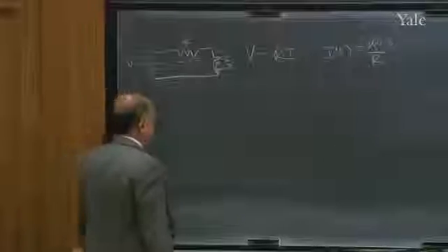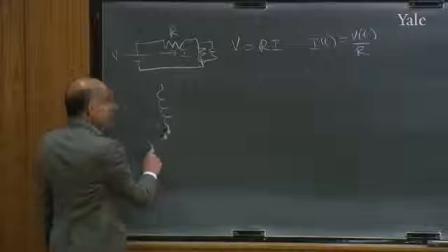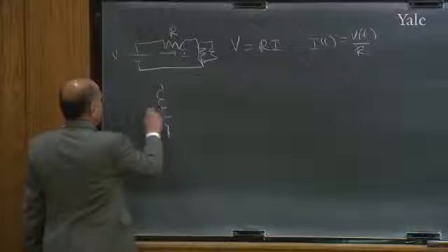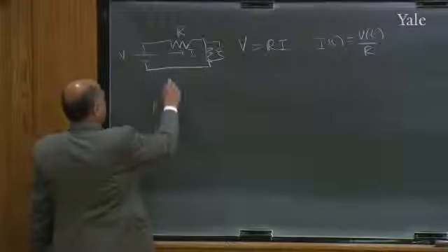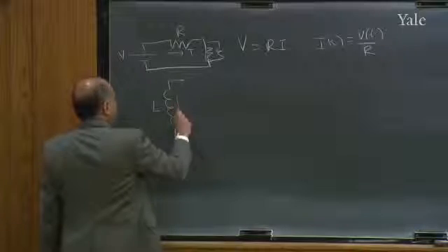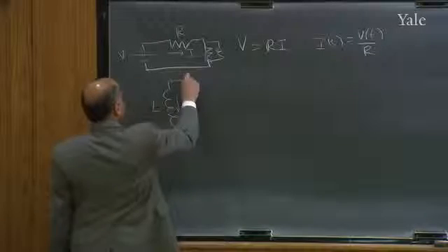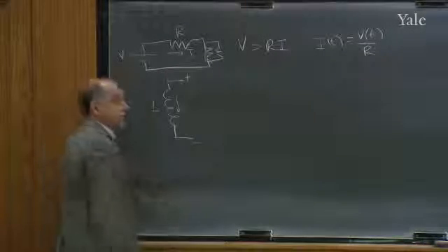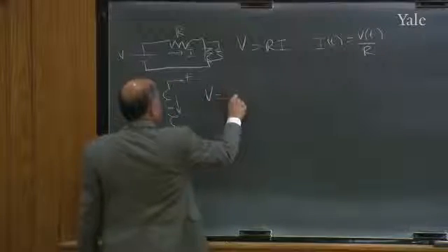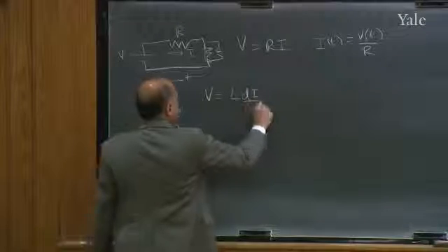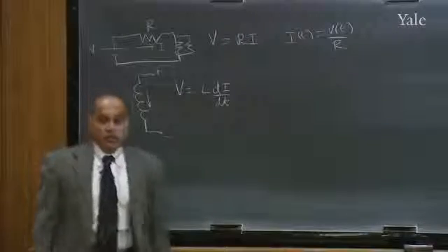But now when you bring inductors, things are different. So I'm just going to tell you a little more about them. So here is an inductor. This is the symbol for an inductor. It's got some inductance L measured in henries. And the implication of that is the following. If you have a current going through this inductor, there is necessarily a voltage with this polarity if the current is increasing. And the voltage you need is L di/dt. This is the bottom line. Even if you skip all the other stuff about conservative forces, this is something you need to know to do problems.